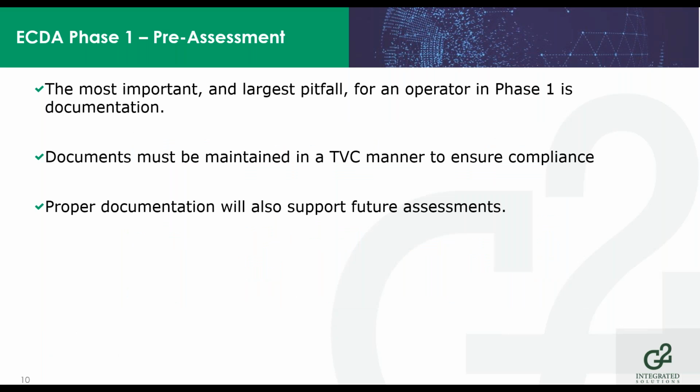So again, the most important thing to remember for the pre-assessment phase is proper documentation. Proper documentation will show that the operator has diligently followed the steps of the process, and that validates compliance with the procedures. Other considerations during your pre-assessment: for first-time ECDA projects, you may want to consider use of a third tool. You may want to broaden your data collection to include more data to help you better establish feasibility and better determine what tools to use, or you may want to make your regions a little more well-defined.